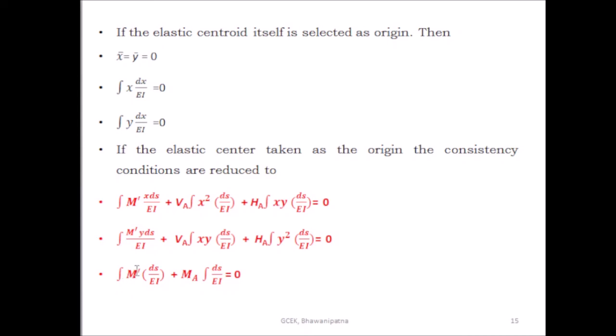Then the third equation, integration m dash ds by EI plus Ma integration ds by EI. So these are the consistency conditions after taking the elastic center at the origin.